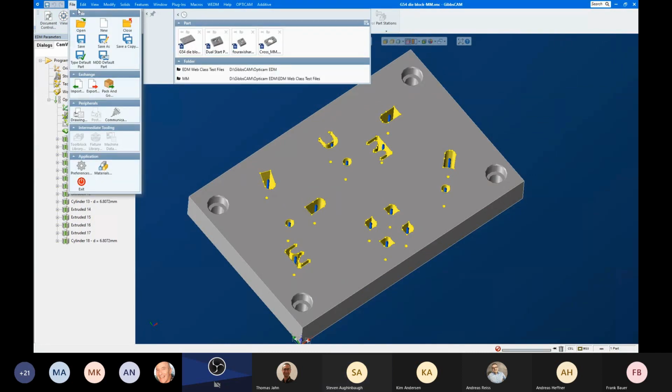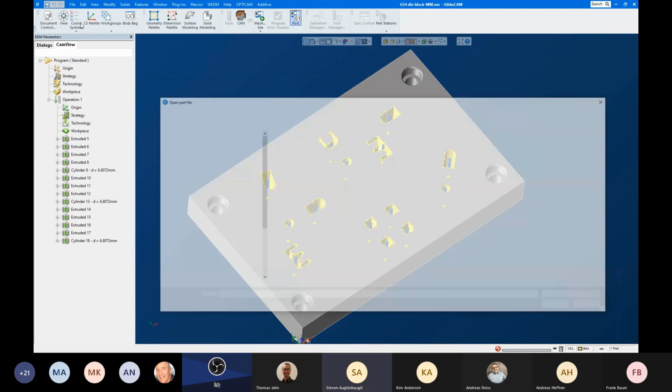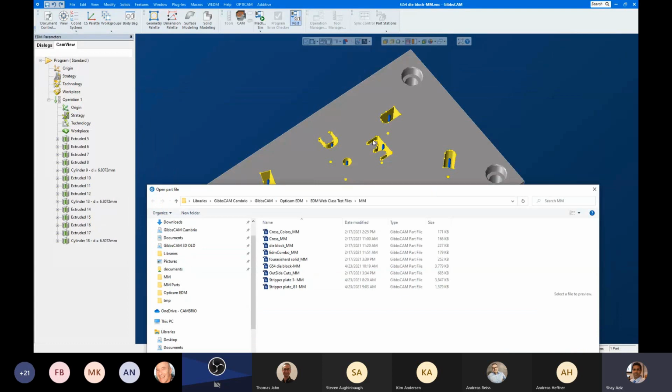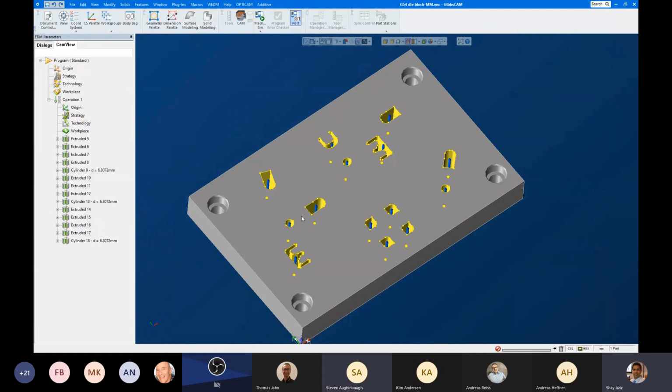Questions about this? Steve, it's Shai. Hi. Can you show me the order of the cutting? It's not dependent on the list on the left. It depends on the path. Can you set the order manually or just automatic? Do you have the option? Yes, you can set it manually. You can actually move these around. You can grab them and drag them around. We were doing this yesterday. But does it define the cutting order also? Yes.